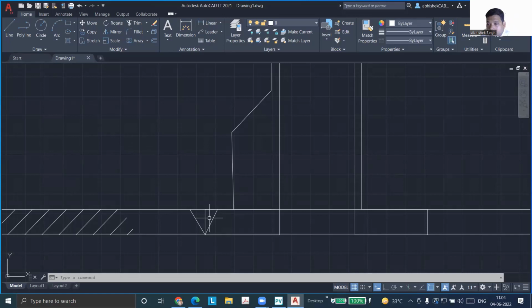Yes, sir. So these are the costliest nozzles and we have to select them when there is no option other than providing full penetration weld and RT joint efficiency as one. In that case, we can go with this, but this will be really costlier. And it is time consuming to procure these forgings and machine them in this shape, because all this will be based on the job.